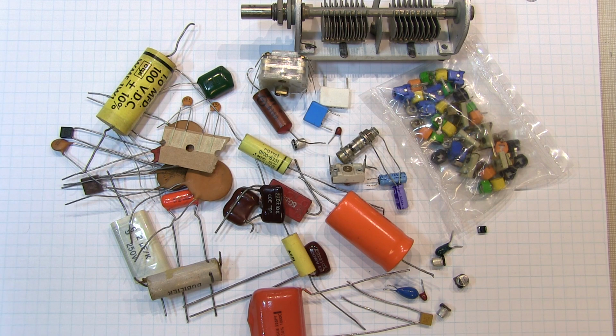And again, just remember that the vast majority of the polarized caps that you see will be aluminum electrolytic or possibly tantalum, and the vast majority of the non-polarized capacitors you see in a design are most likely ceramic, whereas you could use film capacitors or even mica capacitors in those applications, particularly if you're operating over a wide temperature range or at higher frequency.